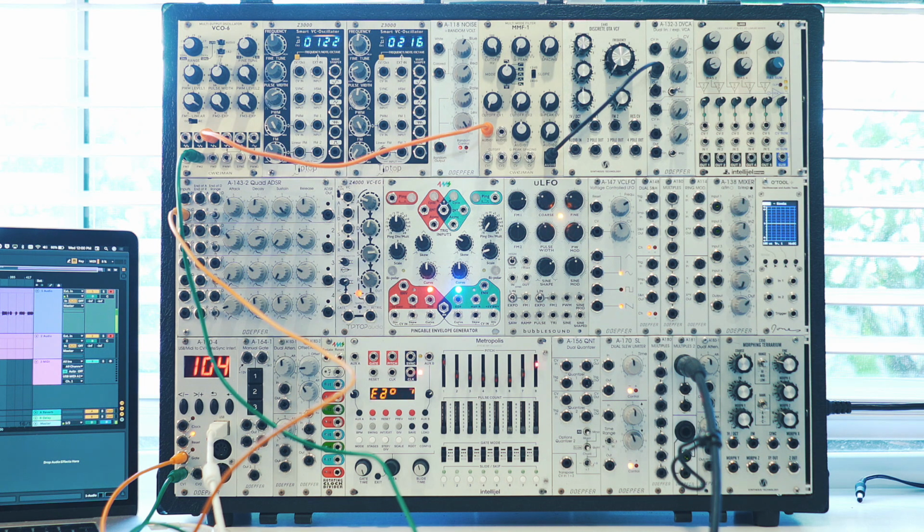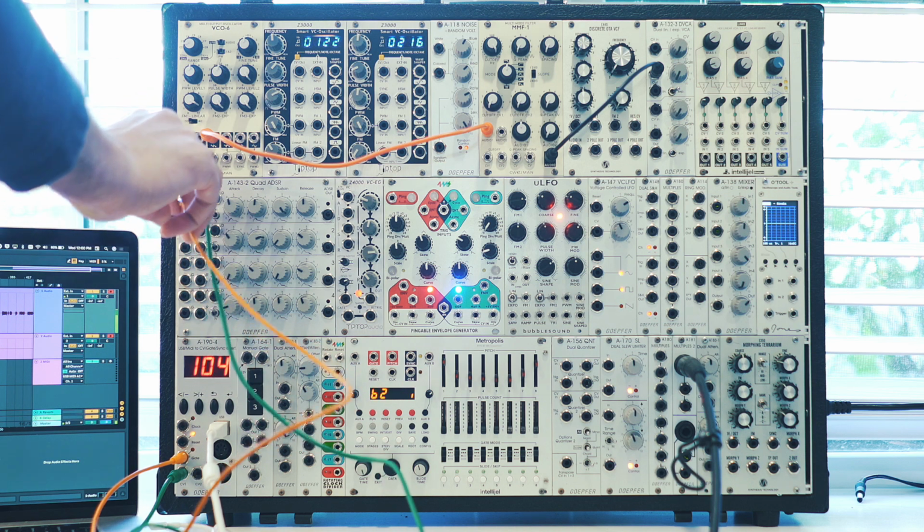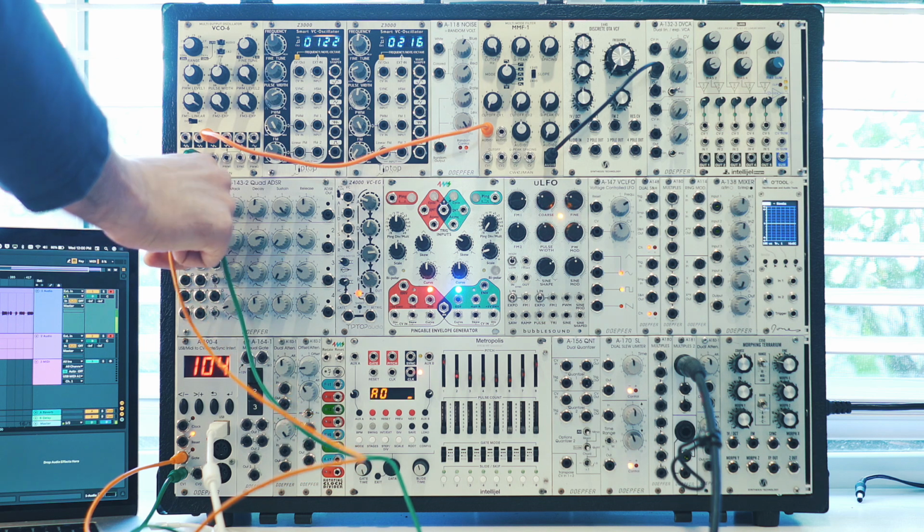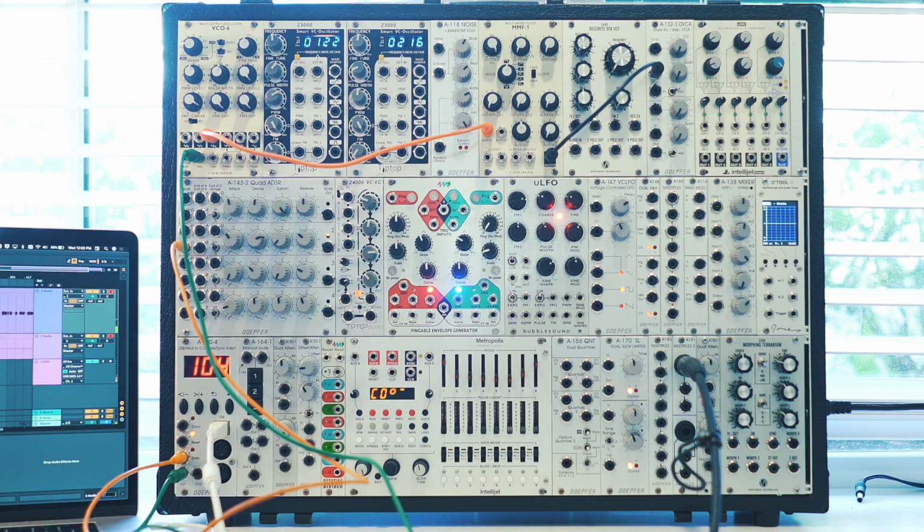And also, if you keep an eye on the Quad ADSR, you'll notice that LEDs are lighting up on that one as well. One very interesting thing with this Quad ADSR is that even if you give one gate input, you can trigger all the 4 ADSRs simultaneously. So you notice we're just feeding this one gate signal over here, but all the 4 ADSRs are being triggered. Now, if I was to plug the gate to the second gate input on the second ADSR, you'll notice that we have now unlinked all the 4 ADSRs, and now the second ADSR is the only one that is triggered when I'm playing notes on the keyboard.